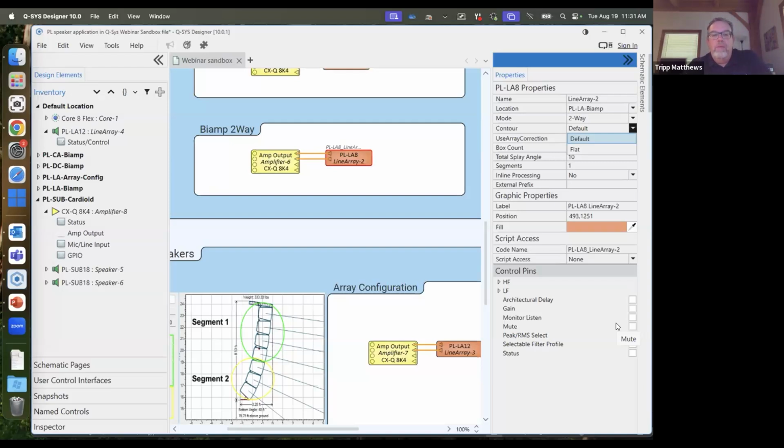If you really wanted to step up your output, you could do the channels in parallel to give you a little more current. But we haven't seen a need for it as these arrays are positioned for your medium level auditorium or house of worship. We're not looking to take over the touring world with these boxes. These are install cabinets.